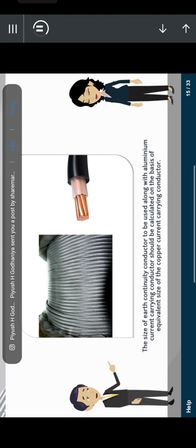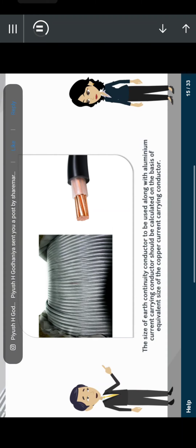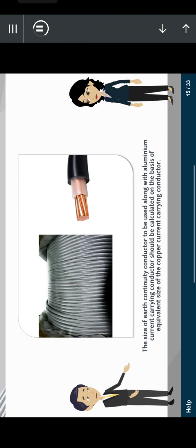Here, another point to remember is that, irrespective of the size or type of an electrically driven machine tool, the bed plate of the machine is earthed by means of a strip or conductor of not less than 6.5 mm square cross-sectional area if of copper, 10 mm square if of aluminium, and 16 mm square if of galvanized iron or steel.